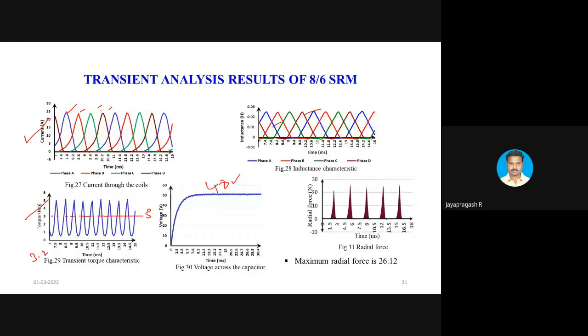Say it is 3 newton meter, okay. But while calculating the torque required at the time of running, we have calculated 9. We calculated 9, but this machine is giving only 3 newton meter. So it is necessary to use a gear arrangement. Using the gear arrangement, we increase the torque by 3 times. Increase in torque by 3 times causes reduction of speed by 3 times. So we fix 3000 rpm, it will get reduced to 1000.